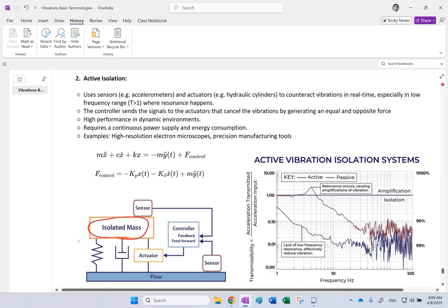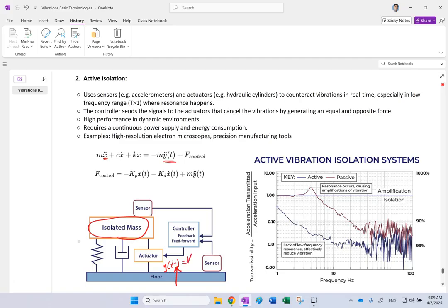By sensing those vibrations, because remember, the solution here is definitely of the same frequency as y. So if this floor is moving with y of t, and that y of t, as I said, is like Y sine omega t, the main frequency for x is also going to be omega. So if I have a way to feel this x of t, I should be able to sense that omega.